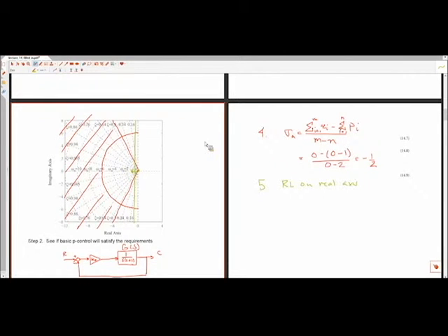As I increase the gain k, the two poles are going to split, and they're going to go along these lines here off to infinity. So as I increase k, we go from having 2 real poles to now 2 repeated real poles, and then also the split complex conjugate poles. As we increase k, it's going to continue to not change the decay rate, but the natural frequency is going to go up, and also the overshoot, all those other things are going to go up as we continue to increase k. So then the question is, will proportional control ever achieve